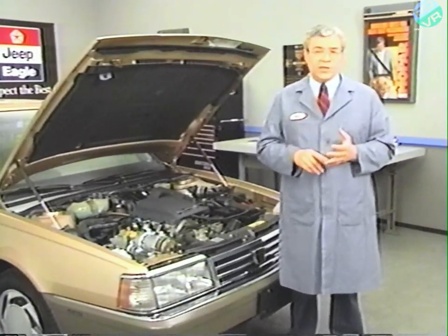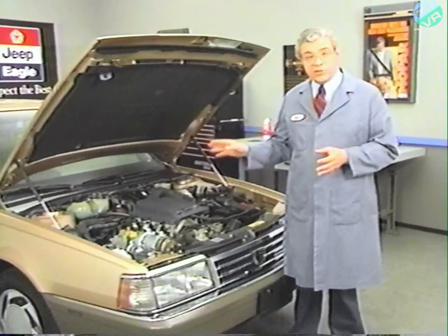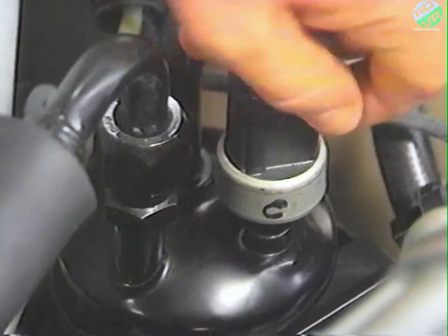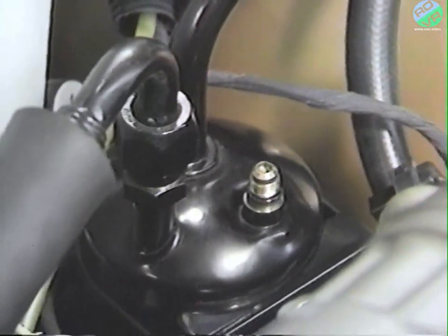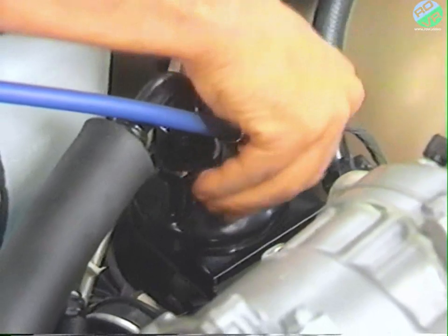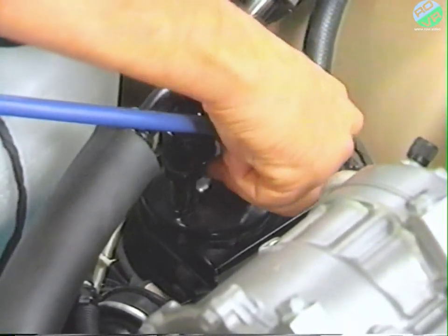One way of determining if system charge is sufficient to close the switch contacts is by connecting a low side gauge to the Schrader valve under the low pressure cycling switch. Make sure the gauge connector has a service valve depressor pin.